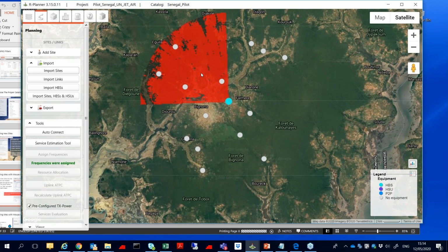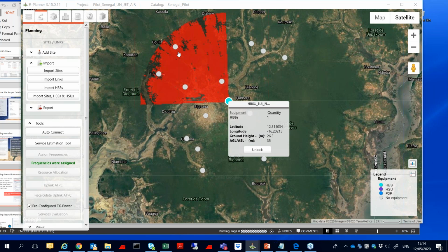And then when we are doing the planning, we need to understand and consider the capability of each product subscriber unit or a point-to-point to provide the performance that we want to achieve according to the antenna gain, the fade margin, the TX power, the modulation, and so on. But the first thing that we need to check is line of sight.